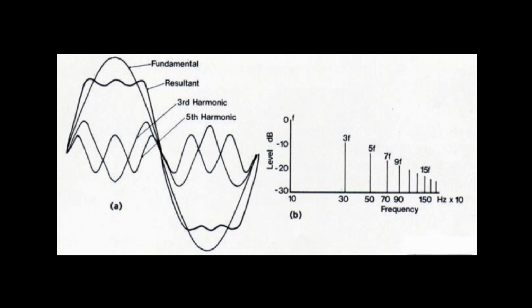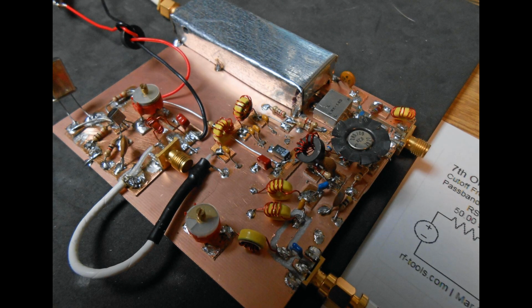Okay, let's talk a little bit about square waves. So I think that filtered sine wave local oscillator that we developed is working pretty nicely in the upconverter. You might ask then, why do I want to try a square wave to drive the LO port on the mixer? We took great care to filter out our sine wave local oscillator in the third video. The idea was to remove the harmonics that might produce more intermodulation products and spurs.